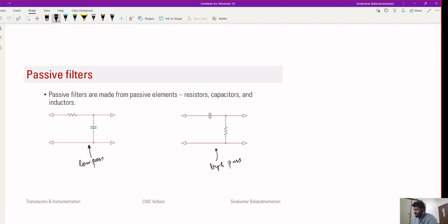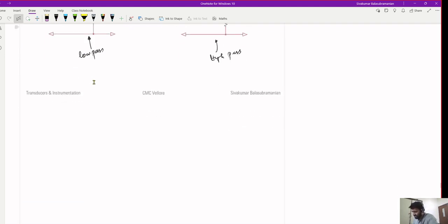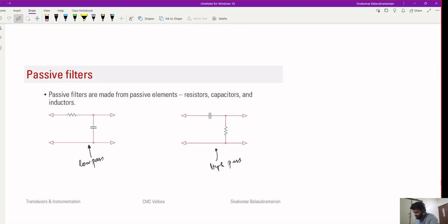So this is one way of building analog filters, right? But it turns out that these have some disadvantages. For example, if you think of this as a block, some filter block, it turns out that if you just use an RC network like this, it has very poor input impedance and very poor output impedance. Okay, same here. So if you simply use these, then these blocks will load whatever it is connected to, and they will get loaded depending on what is connected on the other side.